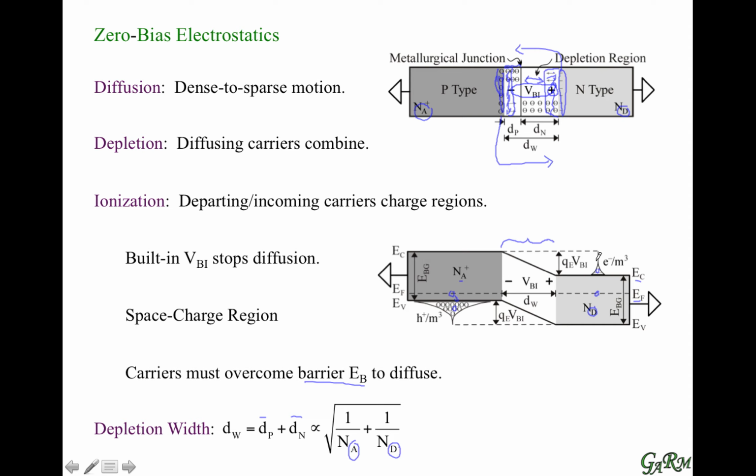And what that means is that basically any electrons that had enough energy above the energy barrier here, remember, here on the energy band diagram, the y direction represents energy. So any high energy electrons were the ones that already diffused over to the p side, and those are the ones that recombined and created this depletion region.